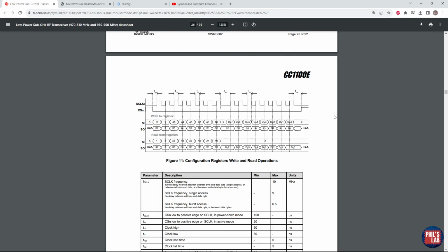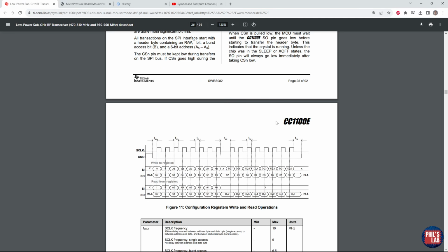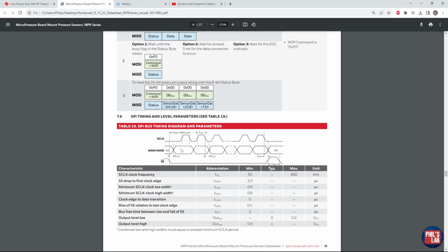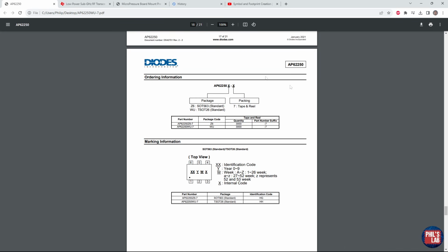Datasheets will of course also tell you, if relevant, about interfaces and timing of the device, for example setup and hold times, timing periods, for example rising and fall times and so on. All the information also contained in datasheets can help you make informed decisions and help you with simulations, for example how long your traces are allowed to be and so on. Also for simple interfaces such as SPI or I2S and so on, you'll see how the interface typically works, what lines there are, and the relevant timing parameters of that device and of that bus. Additionally, what might be important, near the end of a datasheet, is order information, or how, for example, the package code is made up.